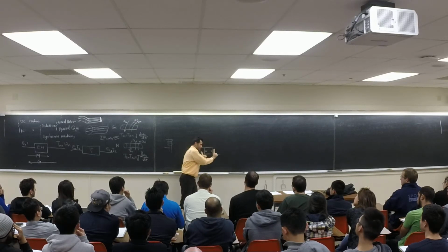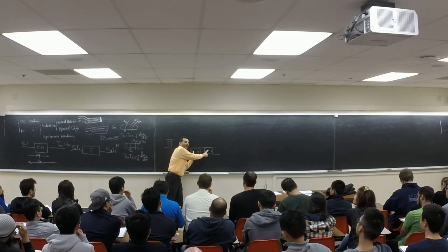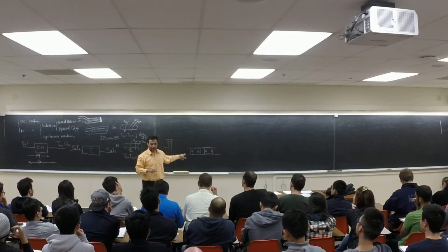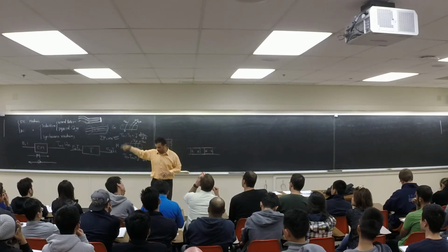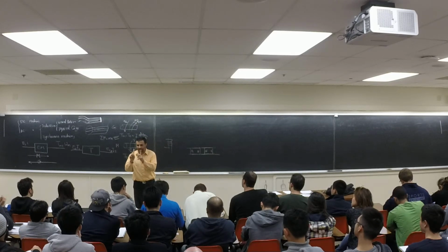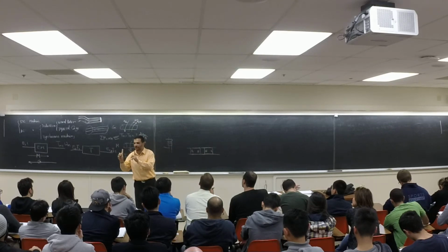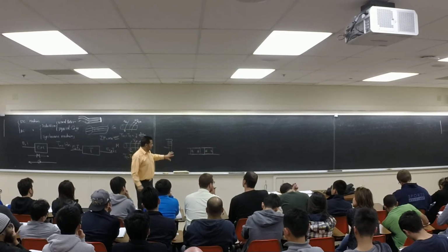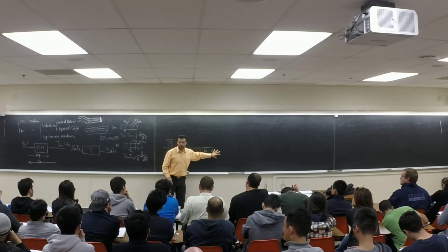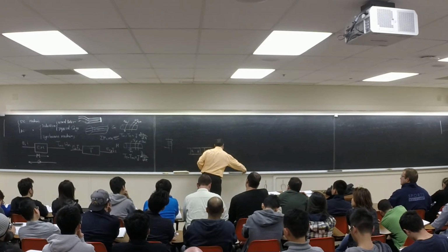Synchronous means you have two magnets. It's as simple as this. You have two magnets, and they are moving or rotating. This is a linear system; when you get to the electric machine, they are rotating. Two magnetic fields moving with the same speed is called synchronous; the word synchronous comes from there. That speed is called the synchronous speed. So for either generators or motors, we have to have two magnets. Now, let's go back to the basics of the generator.